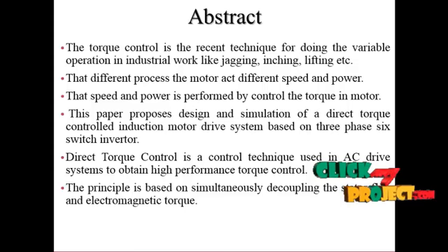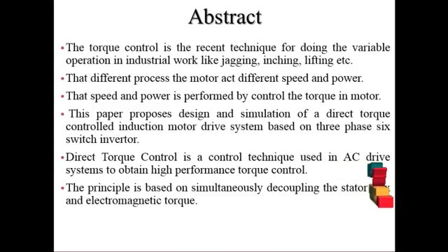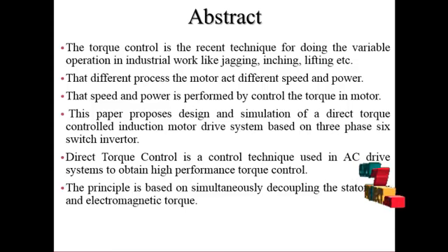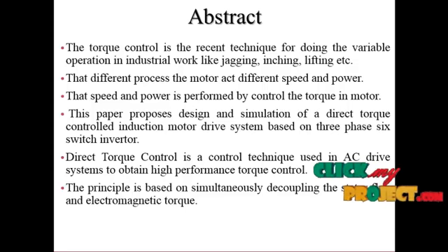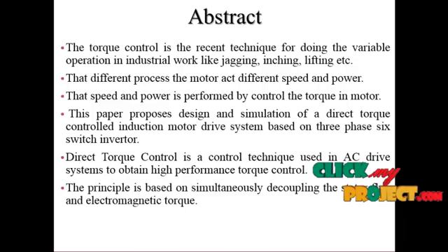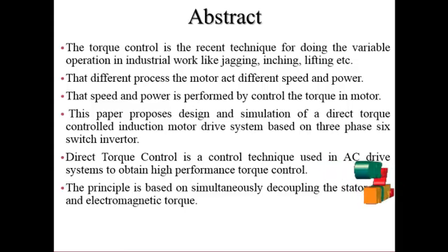In recent years, the direct torque control strategy of induction motor drives has been widely implemented in industrial variable speed applications, introduced in the middle of the 1980s. The first DTC strategy involves a simple control scheme which makes rapid real-time implementation possible. Since then, several investigations have been carried out in order to improve the performance of the original DTC strategy. The major focus features are the uncontrolled switching frequency of the inverter and the high torque ripple resulting from the use of flux and torque hysteresis control.